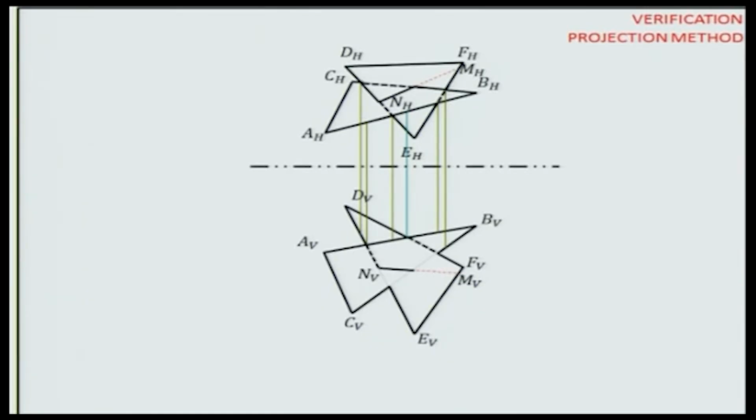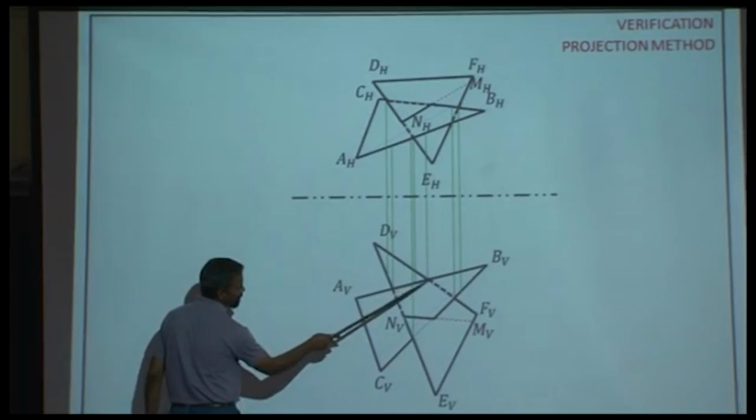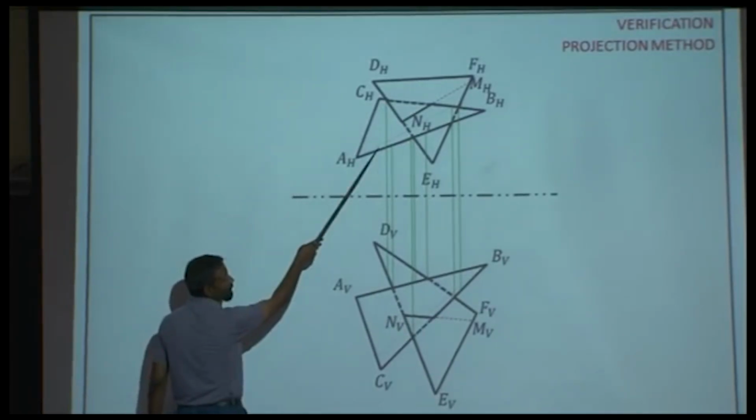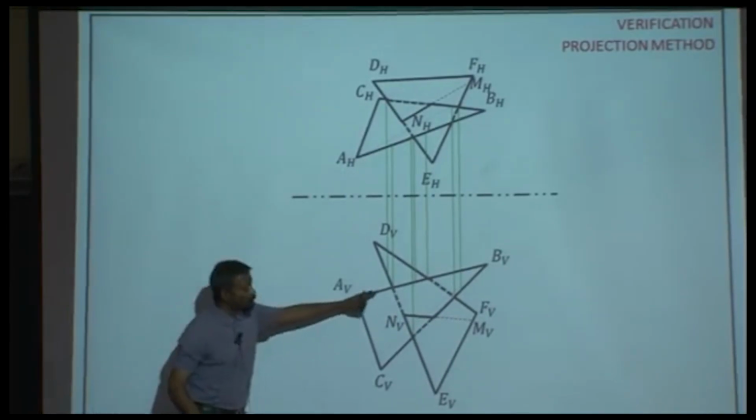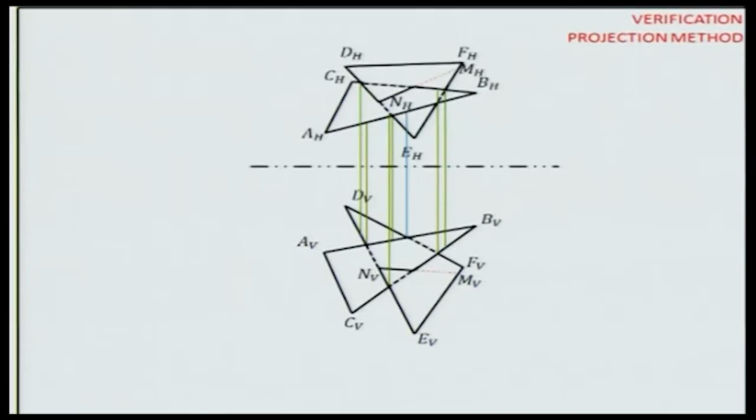Same thing from this view also. So extend a vertical upwards from any of these points of intersections, see which of the corresponding edge is hit before, and that edge is going to be visible in this. Same logic. With me? Everybody? Absolutely confident?